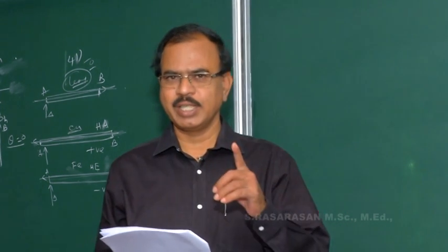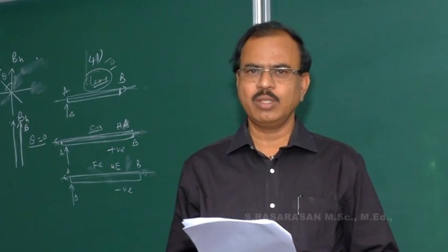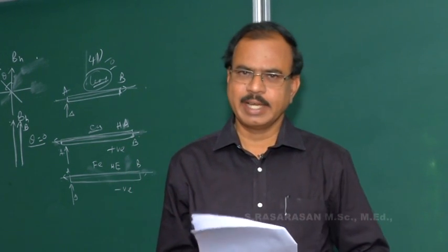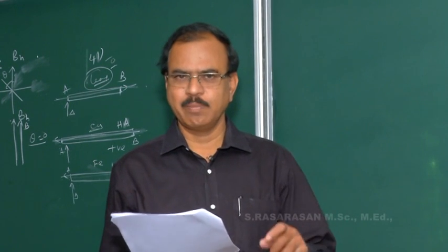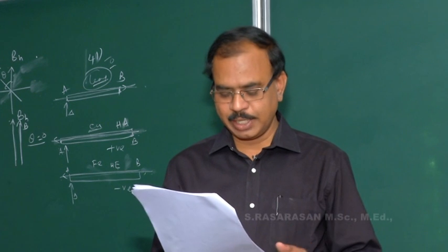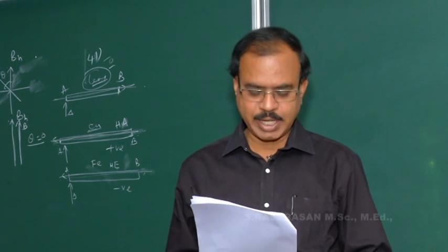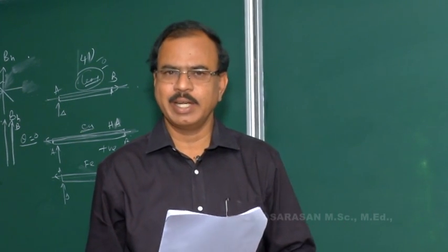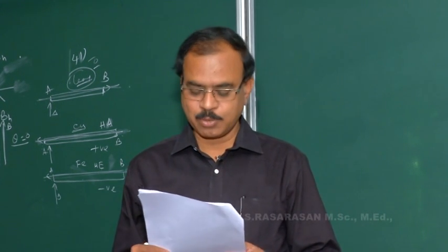That's why we are using lead as a third metal in drawing the thermoelectric circuits, thermoelectric diagrams. So to design the thermocouple, we are using the third metal, lead. Reason: lead exhibits zero Thomson effect. So here in question 41, option C, the heat is neither absorbed nor liberated. No absorption of heat, no evolution of heat, that is option C.